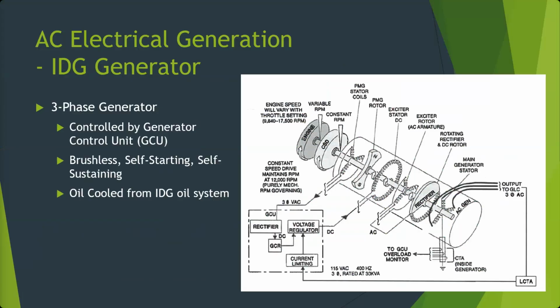These stator coils, I just want to make sure they're not attached to the actual output shaft. Right, correct. Stator means stationary. So they're stationary. This magnet right here is spinning, and that's going to create AC. I can't remember, it's like 36 volts. It's not a great picture. 30 volts. It's enough to run this little box.